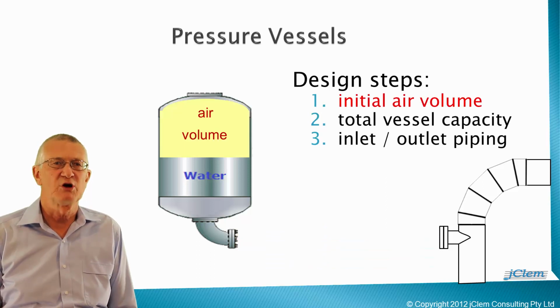Quantifying the initial air volume needs to be the first step because it is the parameter that defines the amount of stored energy available to protect the water system. Actually, it's the initial air volume plus the initial hydraulic level that govern the amount of stored energy. The initial hydraulic level, however, is usually predetermined by the water system's steady-state hydraulics.